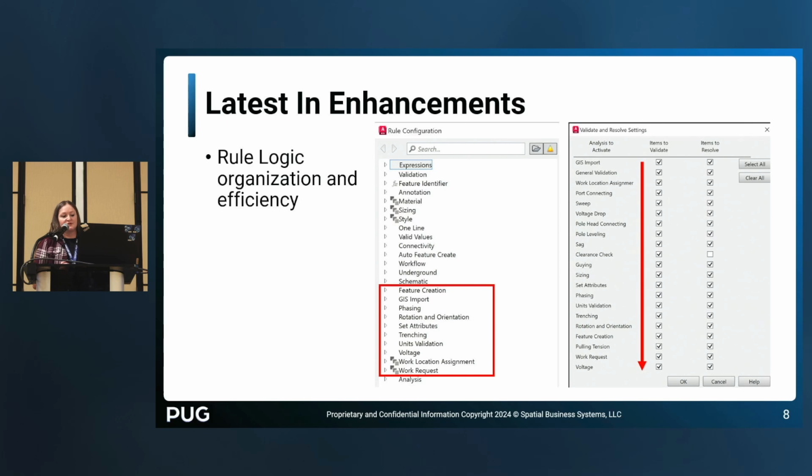this demonstrates where the ones in the red box are all new analysis settings that we added to base config to break up the logic so that we can move certain things around where they make more sense. If something relies on the model name being set, for example, you wouldn't want it before sizing. It should be after sizing. So you can prioritize these.